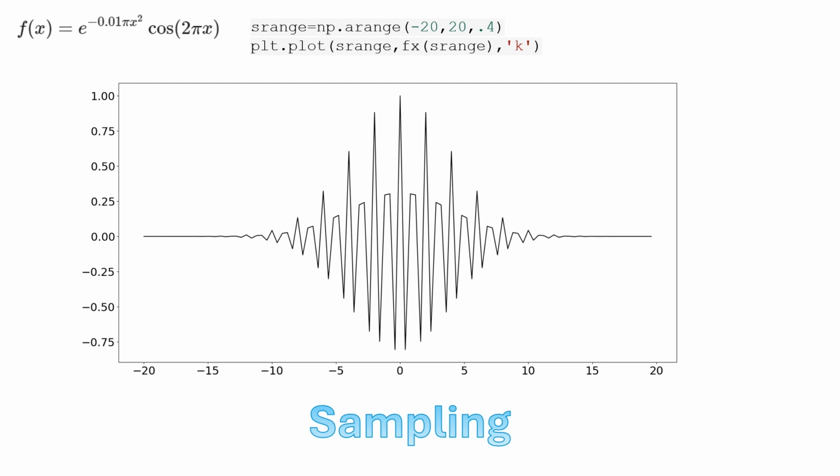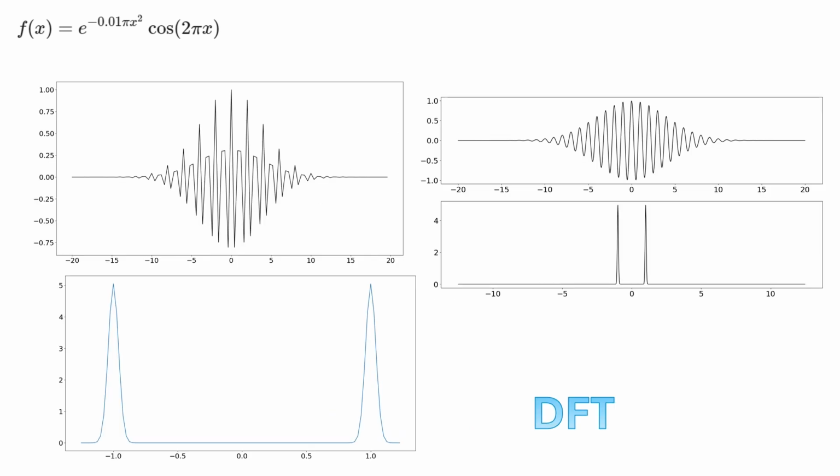So this is what the sampled signal looks like, which doesn't look like the original signal, but the Whittaker-Shannon sampling theorem told us that if we sample at this rate, we can recover the original function. And we do that by applying the Whittaker-Shannon sampling theorem. Looking at these two functions, these are the samples. This is the discrete Fourier transform of this function. This was the original function with a higher sampling rate.